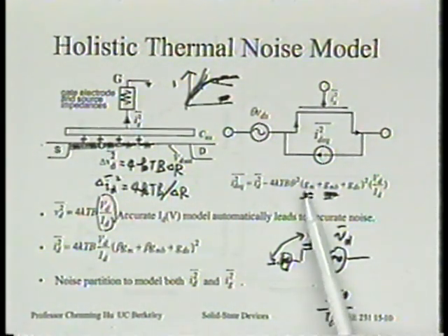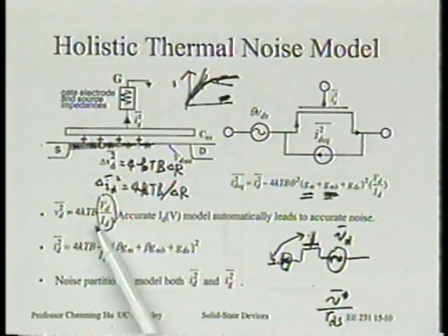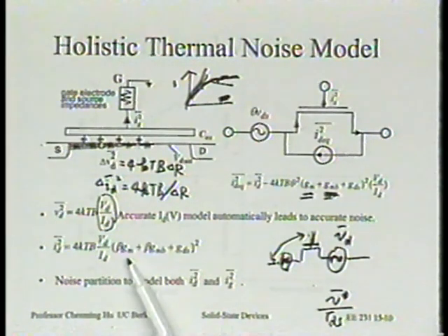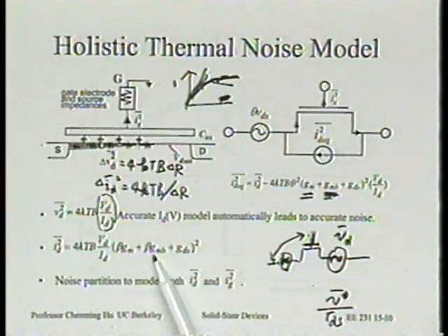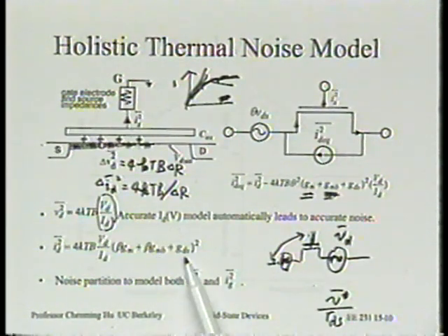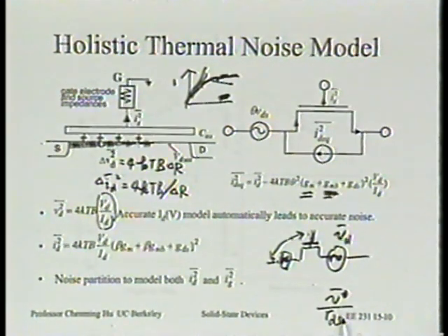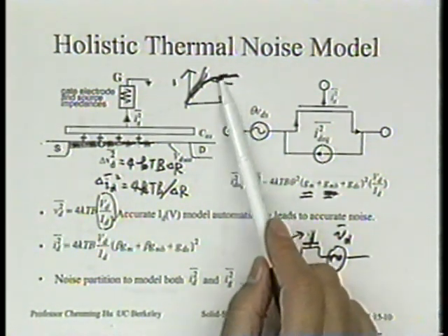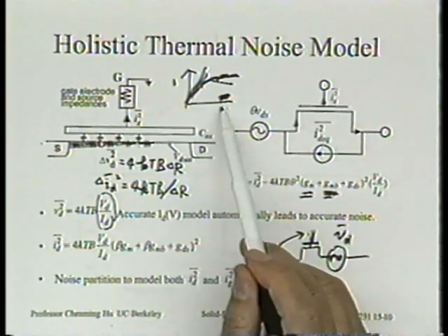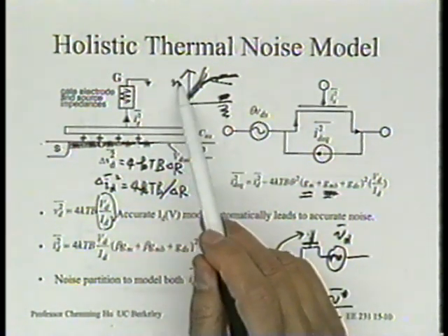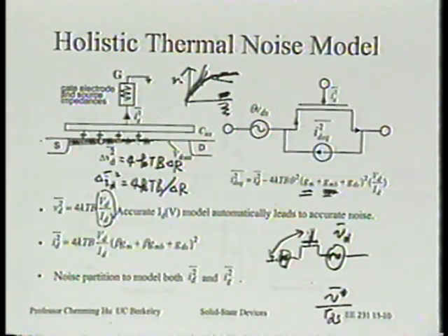So we can see that this noise voltage is translated into current in three ways. One is amplified by the front gate. Two is amplified by the back gate. Three, just as a result of the RDS or GDS. Remember what we said earlier? Anytime there's output GDS, then an AC variation in the VDS is going to give us an IDS. Is that right? So what does beta mean? Now this is coming to the compact model. In order to have a compact model, we have to be able to model this in a simple way.